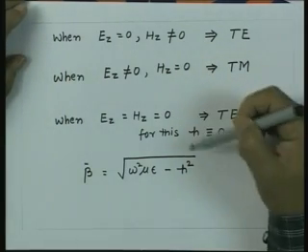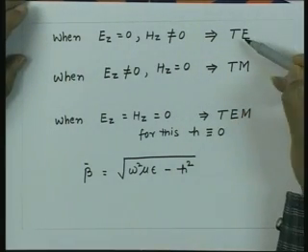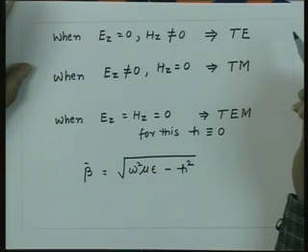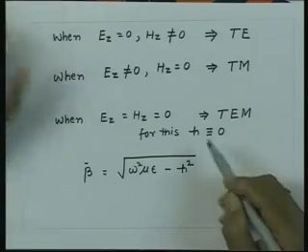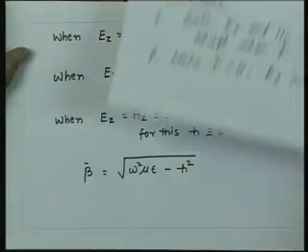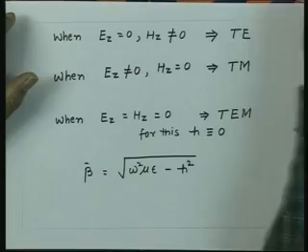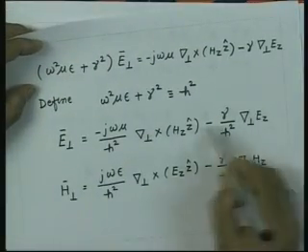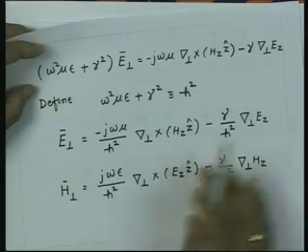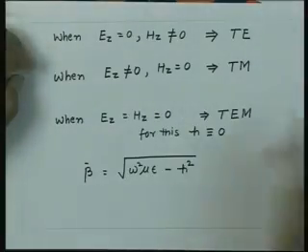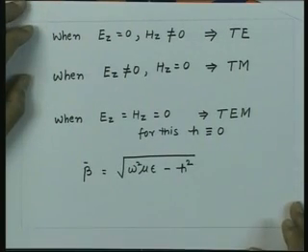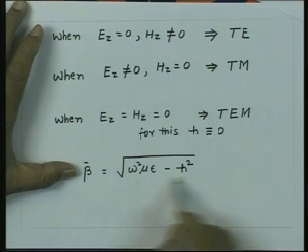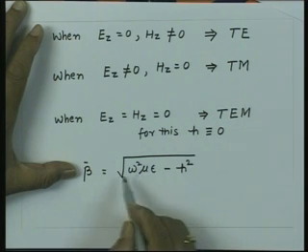So the important conclusion which we draw here is that whether we take a transverse electric case or a transverse magnetic case, in this case h cannot be 0, because otherwise the transverse fields will become infinite if h goes to 0. So when any of these Hz and Ez are not 0, h cannot be 0, that means h is always a finite quantity, or the velocity related to this, that means the phase velocity, will be a function of frequency.